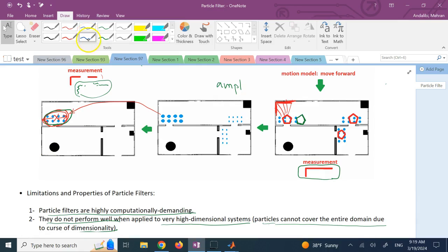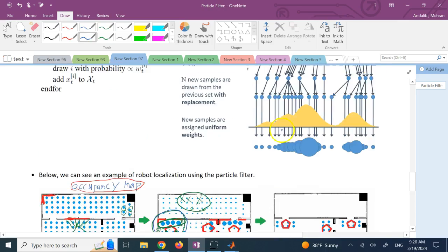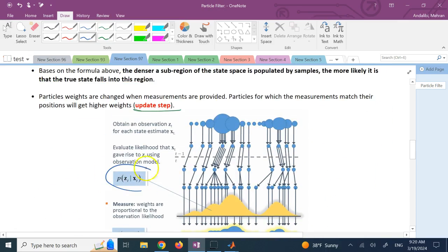On the other hand, this guy would only see a line, which will give me a very, very small likelihood for such a measurement. So although this one was the dominant one and the accurate one, guess what? Now, because this motion model is wrong and my robot is estimated to be in the wrong location, my sensor measurements, although being very good, are completely wrong. And these two cannot be compared. And so this likelihood here is going to be very bad.